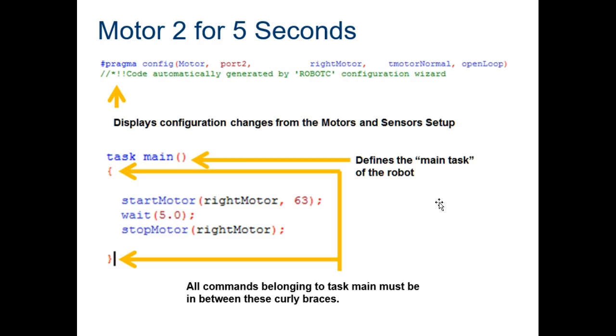Another thing that makes it frustrating is that as your battery starts running down, let's say it's down to half a charge, that deadband can get bigger. So when you're using low speeds, it might be a good idea in your robot design to use a gear system to slow the motor down, so you're turning at a higher rate on your motor and getting a slower speed through the gear system.